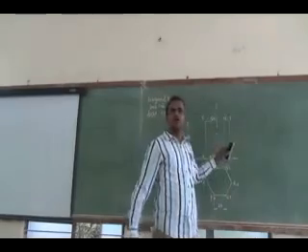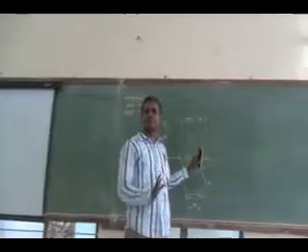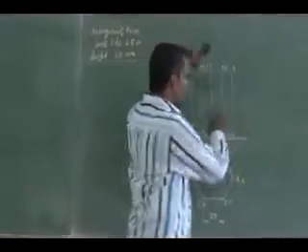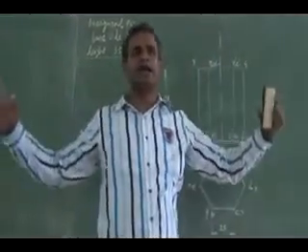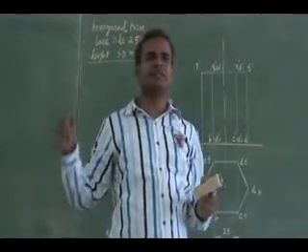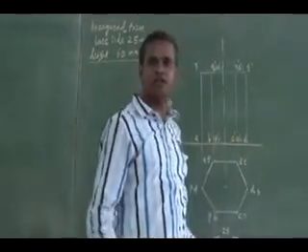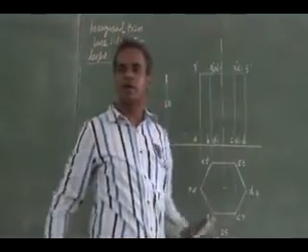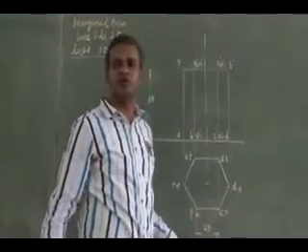You draw the projection for this first of all, quickly. Draw the projection with an H pencil. Right. I ask you to draw the development of the prism. You need not draw the projection if it is a problem like that. I know it is going to be 6 rectangles of side 6 into base, that is 25. 6 into 25, that is going to be the length.